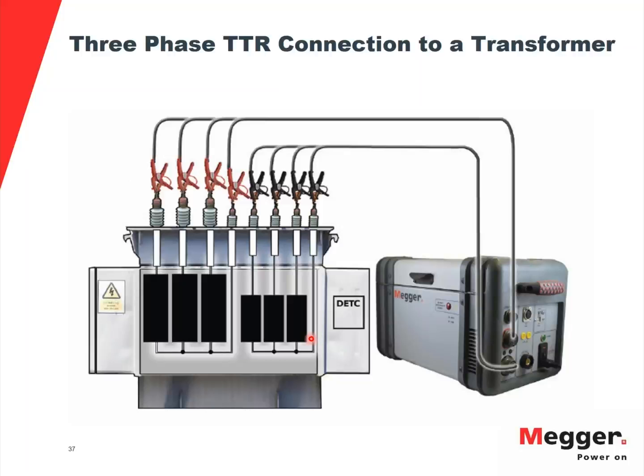We run into these questions from the tech support point of view: people testing small dry type transformers or small pad mount transformers, oil filled pad mount transformers, and they cannot pass the 2% criteria between the phases or 5% from the factory. In those cases, it's not that your transformer is bad or anything. It's just that 2% is too low a resolution for any test instrument to give you that kind of accuracy.